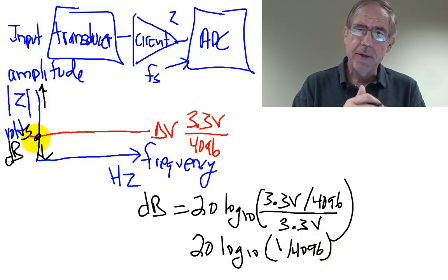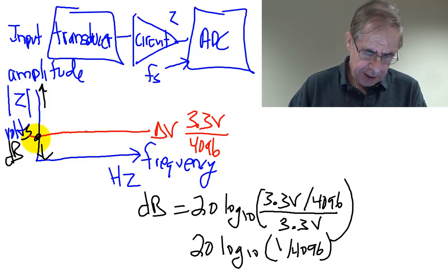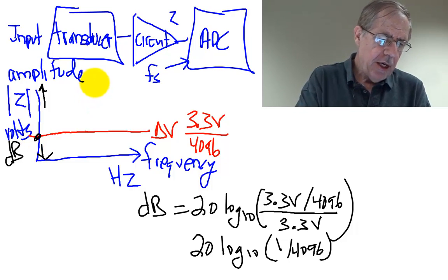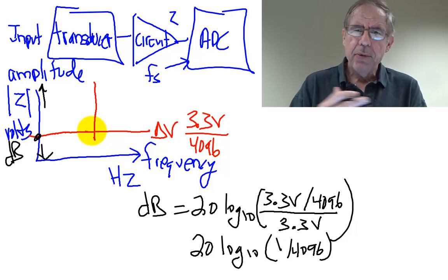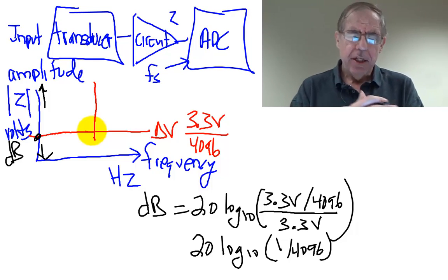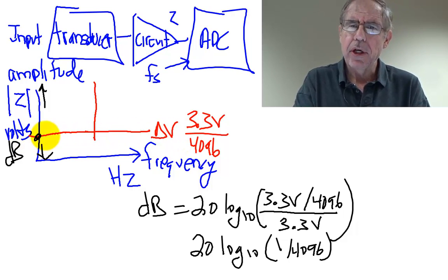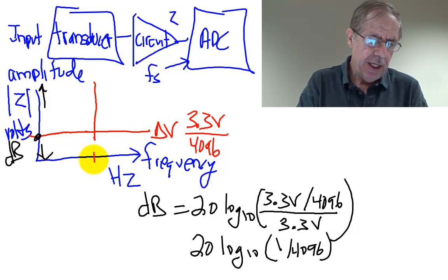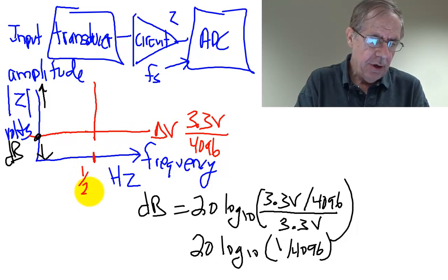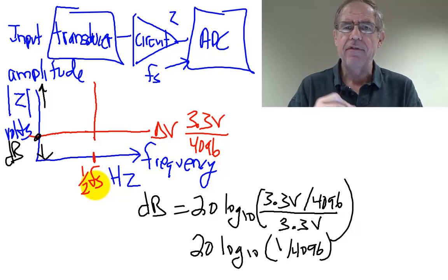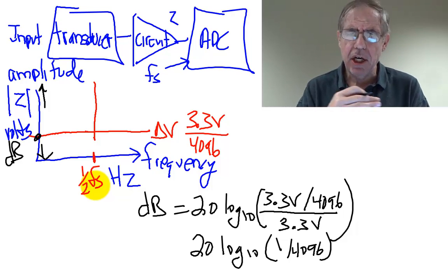Now the interesting part about this curve is to think about the three regions defined by, on the amplitude axis, where we define the resolution. And on the frequency axis, I am interested in 1/2 Fs. That's the aliasing cutoff.